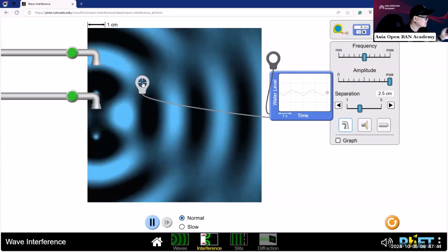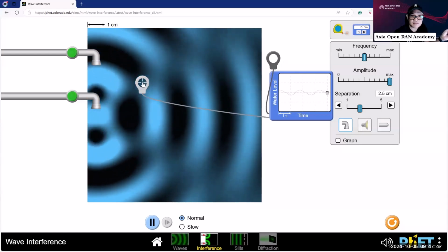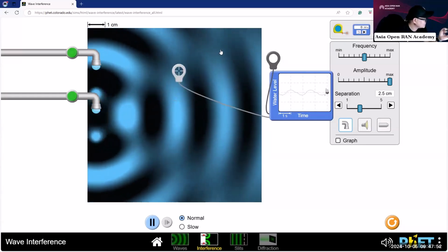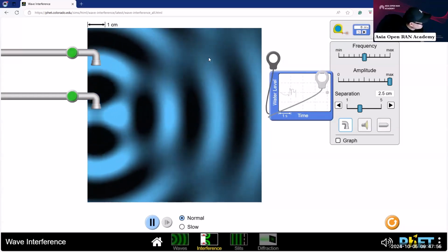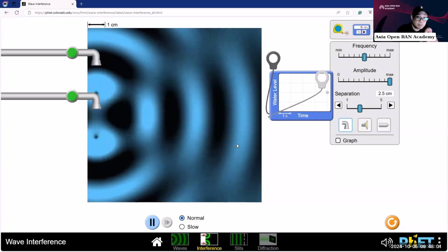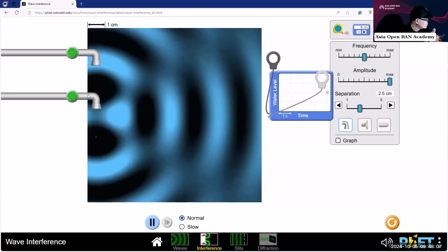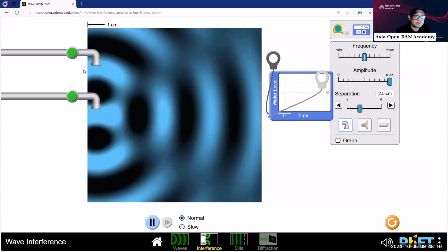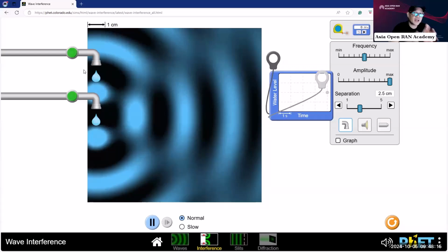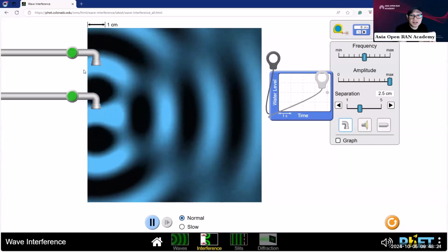So this principle is used in massive MIMO, especially in the technology we call beamforming. By adding multiple antenna elements, you can control the beam of your antenna. You can focus the beam of your antenna in a certain location. Imagine, that's only two. We are only using 2 antenna elements. Imagine if it's 3, 4, or 100 plus antenna elements. You will have the capability to steer the beam of your antenna.